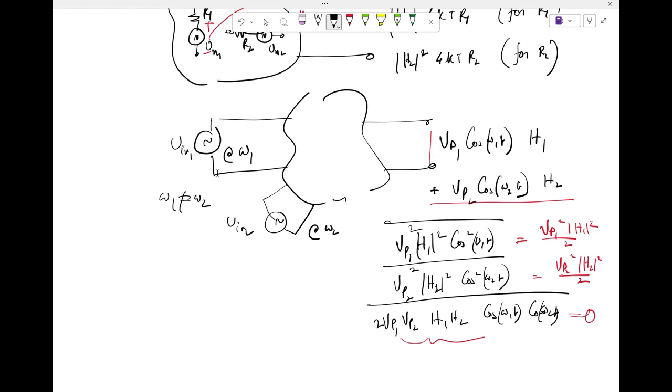If you are comfortable with correlation, then it is equivalent to saying that the cross correlation of the noise sources is equal to 0. That's because each noise source is uncorrelated with its neighboring noise source. So there is no correlation between the noise from one resistor and the noise coming from another resistor. When you multiply the effects and do an average, the average will go to 0.